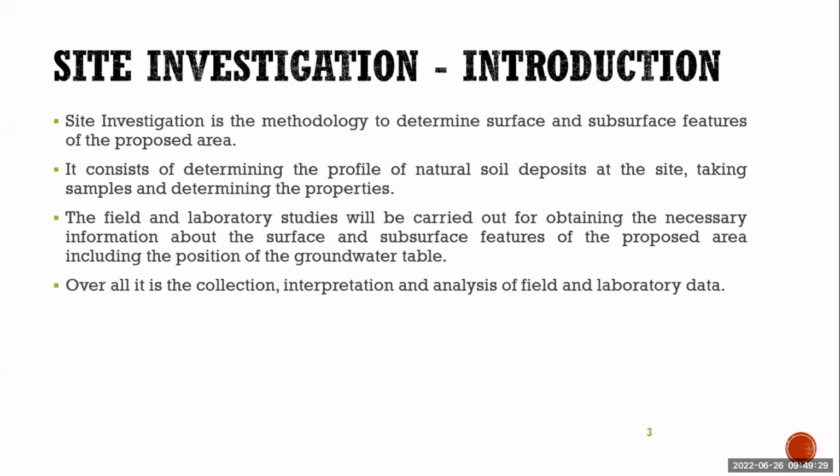Based on site investigation, we have to know the soil properties. What properties? We will know cohesion, which is the intermolecular attraction between the soil particles, then angle of internal friction, permeability, and compressibility of the soil. Based on the compressibility, we can say if we build any building there, how much settlement can happen, how much it will compress. That is called compressibility. And if you are constructing a dam, we need to know the permeability of the soil or permeability of the rock.